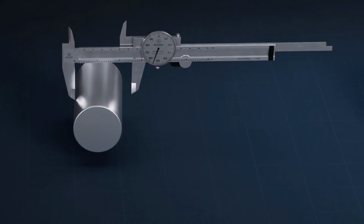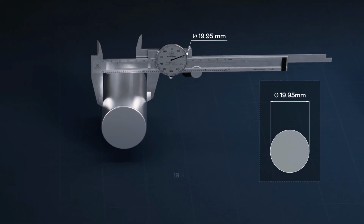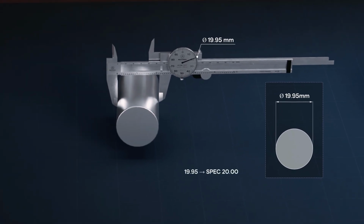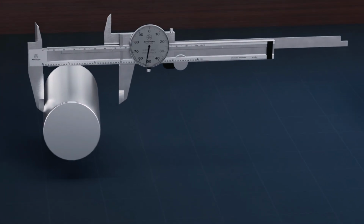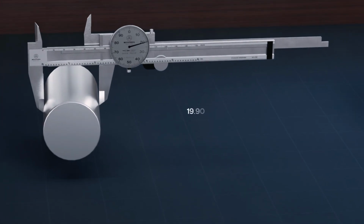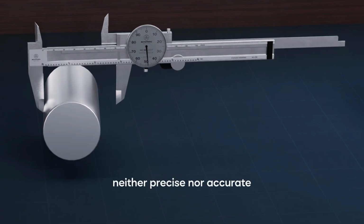In the first case, the micrometer measures the shaft as 19.95, 19.95, 19.95. Every single time. Those readings are very consistent, but they are far from the true value. This measurement system is precise but not accurate. In the second case, the micrometer gives readings like 19.90, 20.05, 19.85, 20.10. Now the readings are scattered. This system is neither precise nor accurate.